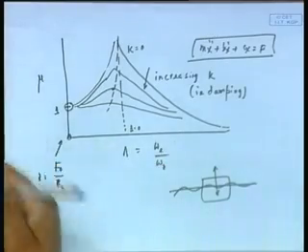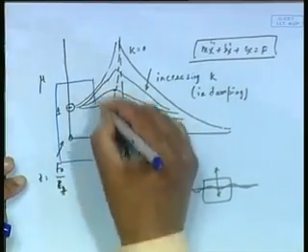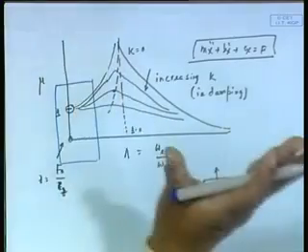You don't even know that there is a wave coming, because you have actually just gone up and come down with the water. So as you stand, you always look at the water, you don't feel you are moving. First of all, omega is small means Te is very large, so it takes all the time. Just imagine it takes 10 minutes to go up 1 meter, so how do you feel it? So this is one extreme of this graph, this part, and we can call this region hydrostatic motion. That is, this side of motion is dominated by hydrostatic force. It is the hydrostatic force that dominates.